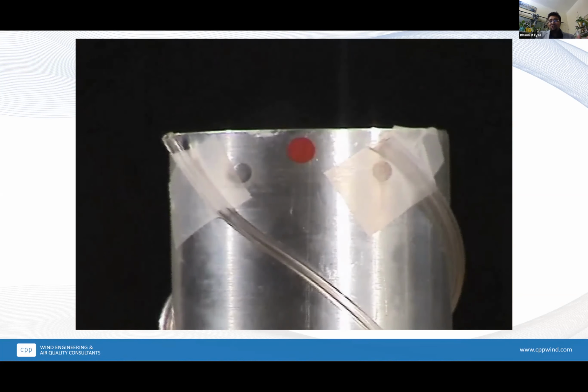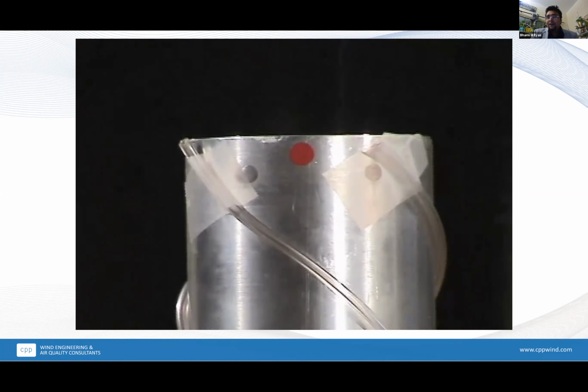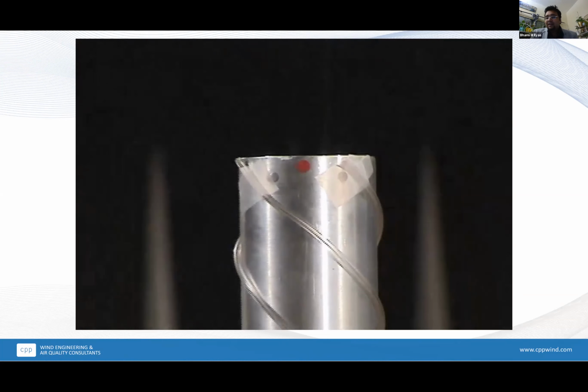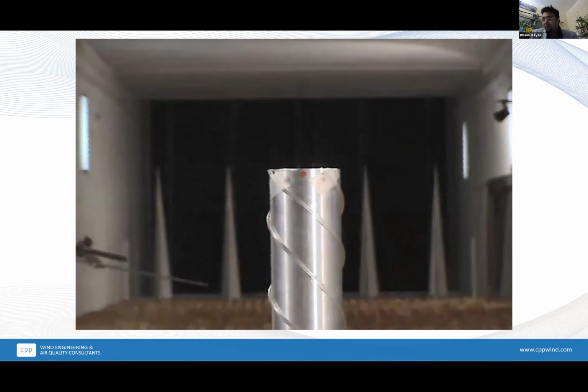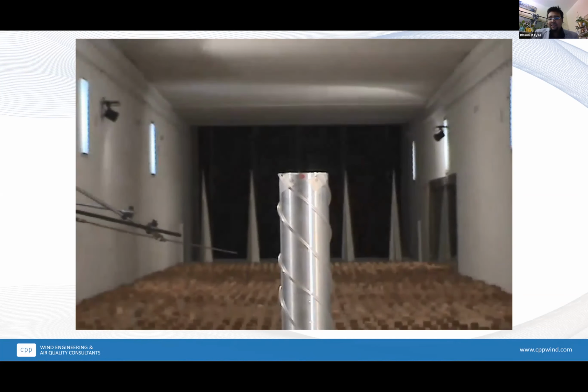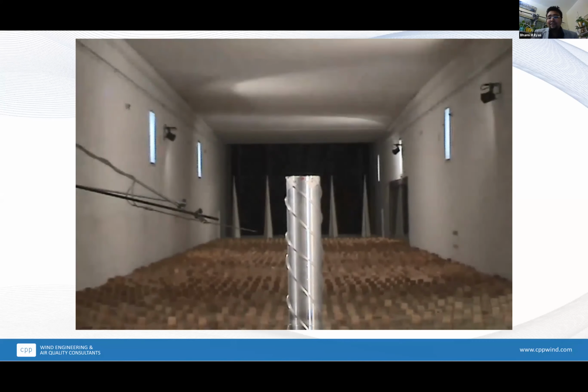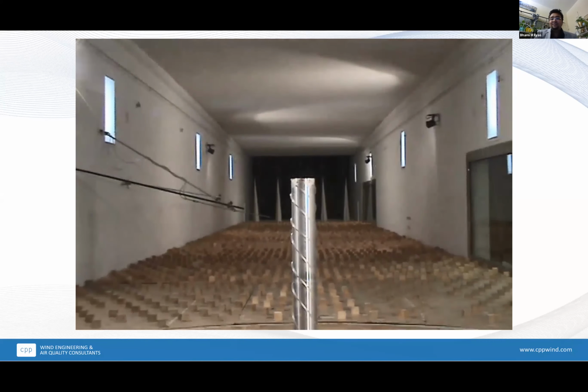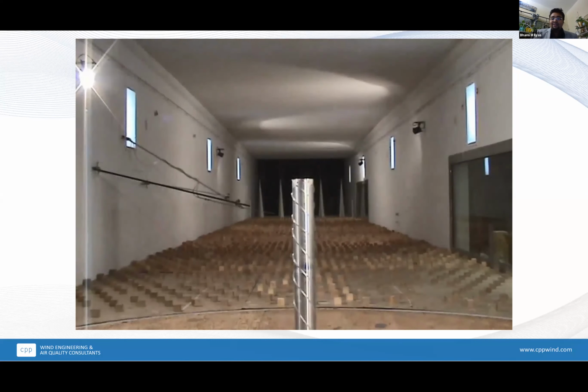Now if you recall this particular cylinder and helical structure, you would have noticed it somewhere else. And this is in industrial chimneys. This particular design is very prevalent, and that is the reason why you see this in industrial structures. They have helical streaks to actually reduce the shedding.